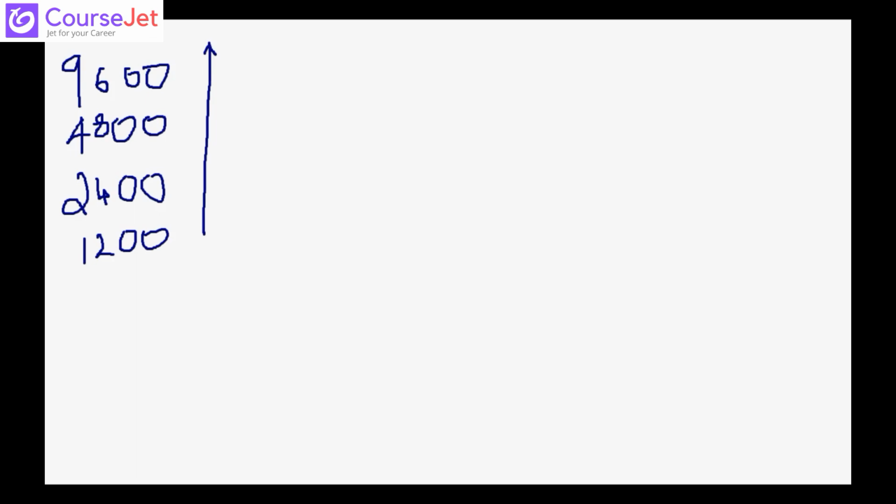Now how are we getting this baud rate? That means I have to send 9600 bits per second. So what to do, and how to receive this? First of all, we use a particular frequency, the 11.0592 megahertz crystal oscillator.